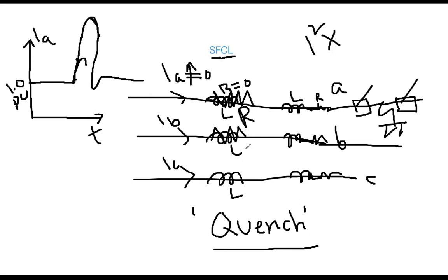So this means quench happens, and then also the circuit breaker opens, but immediately it cannot transfer from quench mode to superconducting mode. It takes some time because already its superconductivity got damaged and it gained a high value of resistance. So it takes some time. This is called the quench extinguish time. To get back to that superconducting mode, it needs some time.